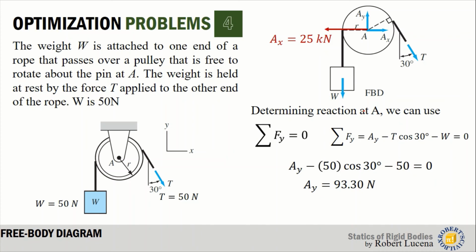So again, if you replace the support with support reactions, make sure you are knowledgeable in how many unknowns you will draw. But the direction could be smartly assumed. However, if you get the wrong direction, you can know the right direction after analyzing the equilibrium.